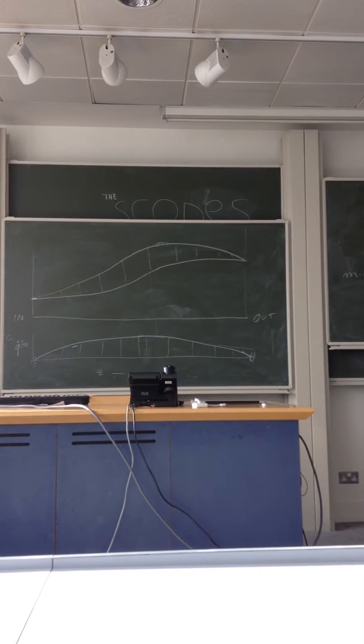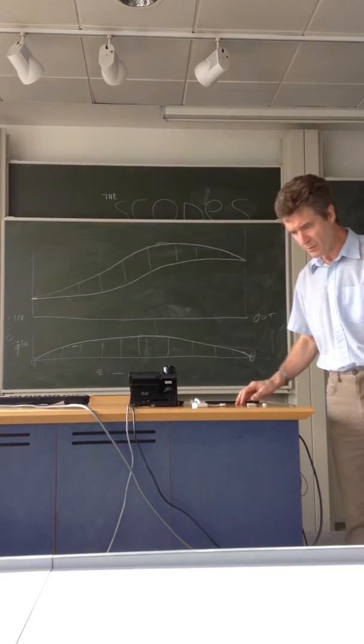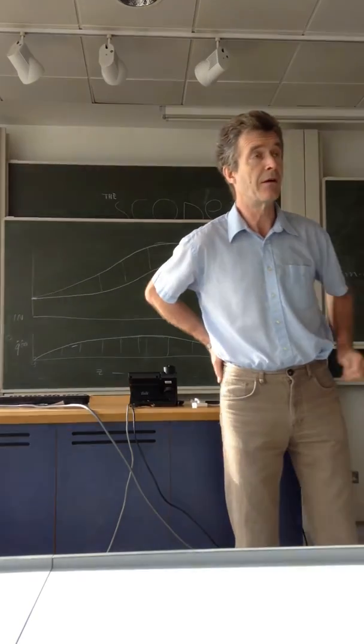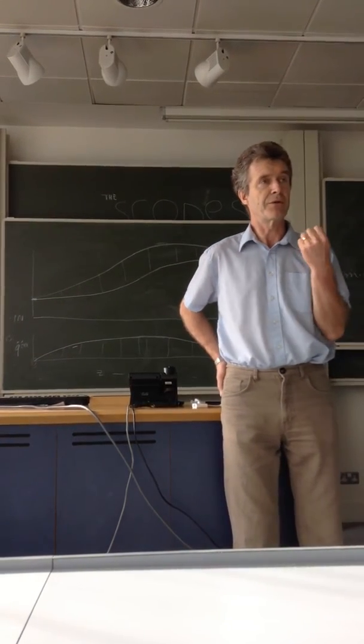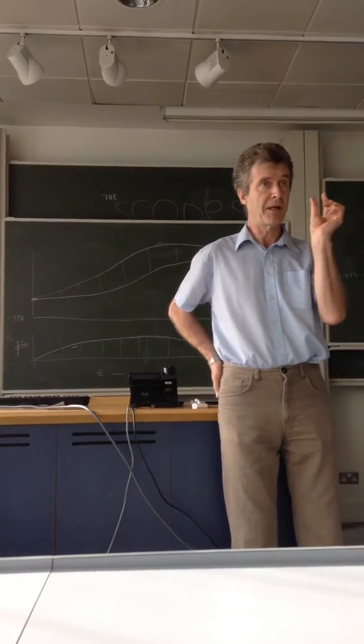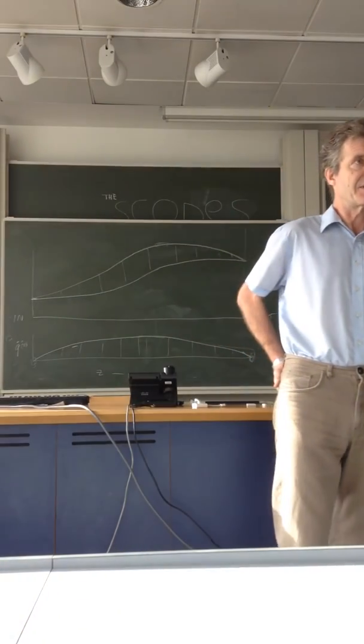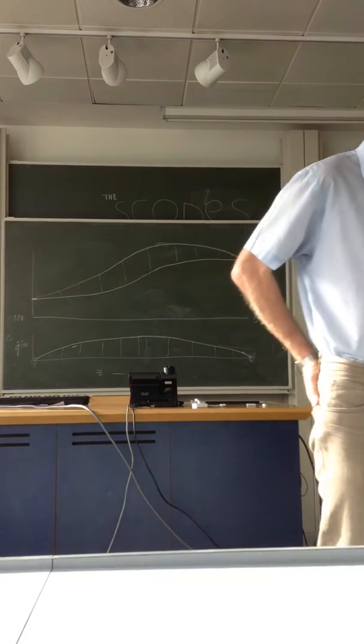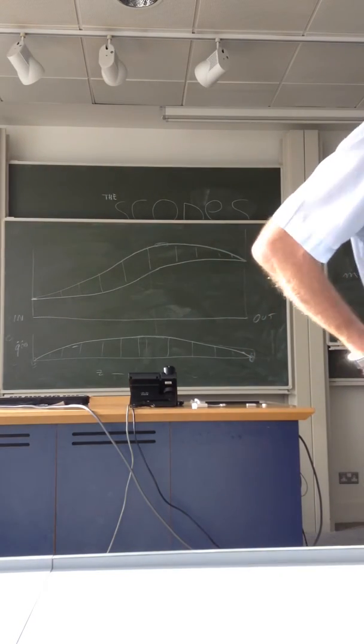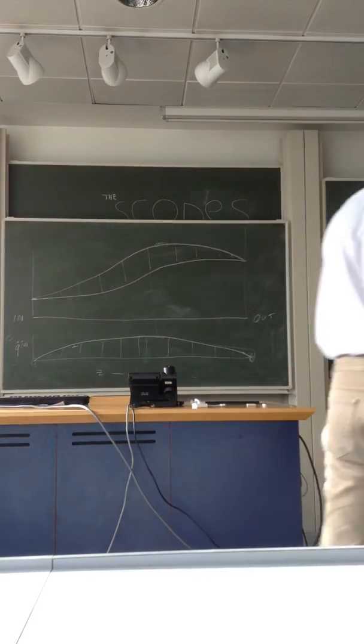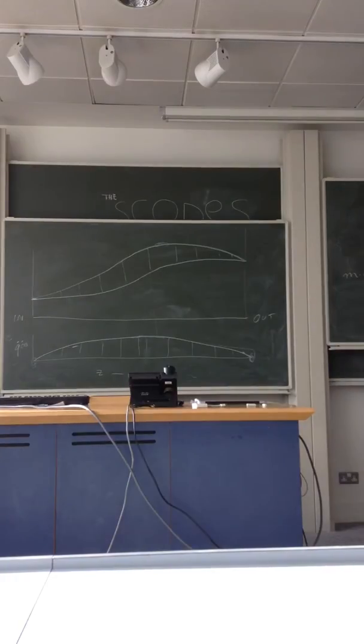Now, we do the integral up there to get the temperature of the bulk coolant, and then the temperature of the cladding, of course, is that bulk plus the boundary layer delta T. I'm not going to go through the algebra on the board, you've got all that in the notes there. The boundary layer delta T, of course, is proportional to the local rating, so that's proportional to the cosine term as we go on. So that gives us a relationship for coolant and cladding temperature versus axial position.